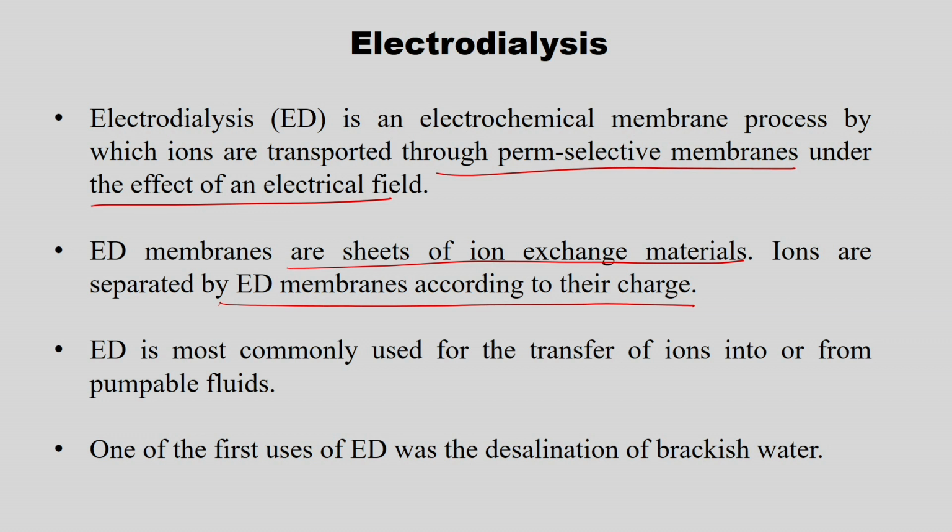So, ED is most commonly used for the transfer of ions into or from pumpable fluids, right. Whether to remove the ions or add the ions, as we mentioned in food processing sometimes. If any nutrient quality is deficient, we can also add them during the process to get the particular nutrient level. So, one of the applications may be the addition of ions, ionic components. ED is most commonly used for the transfer of ions into or from pumpable fluids.